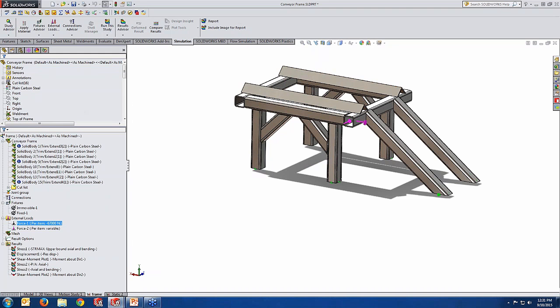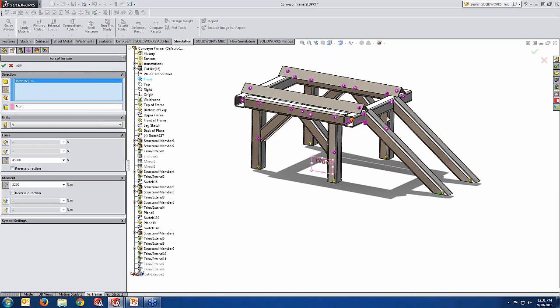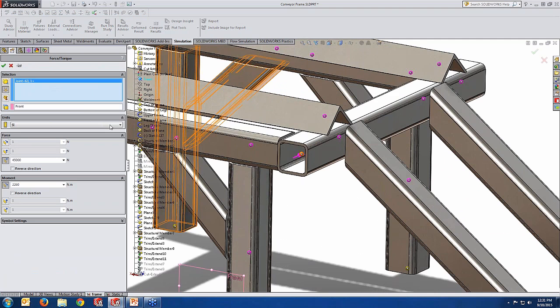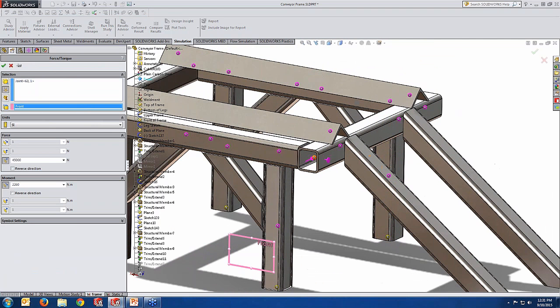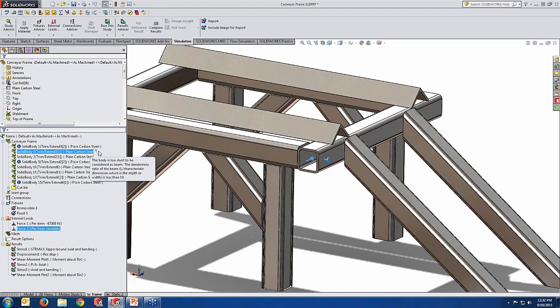This is a distributed load on the beam, and my other force, as I said before, is considering a joint, which is that corner joint you can see here. According to a front plane, it has a normal of 45,000 Newton load, and it got a moment of 2260 Newton meter on the same long direction 1. So you can add more or less here, or simply not consider them. So I have defined my problem as it was described from the beginning.